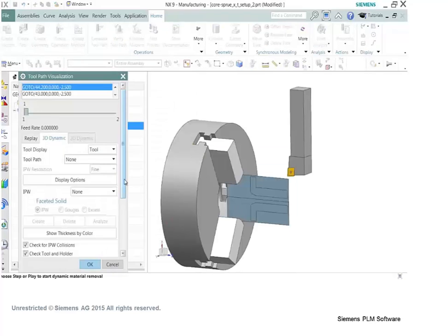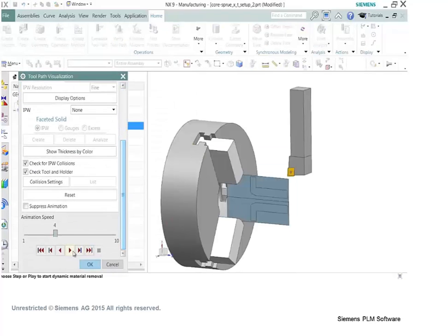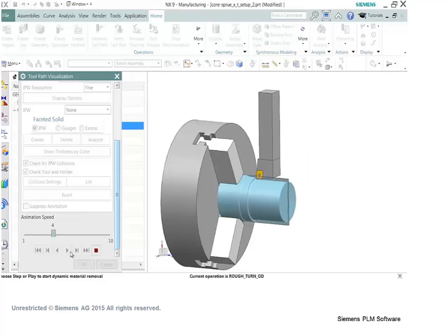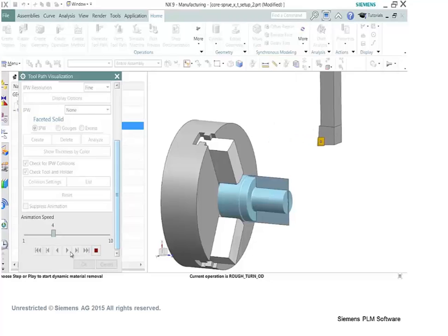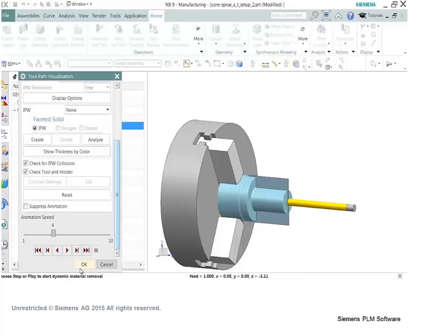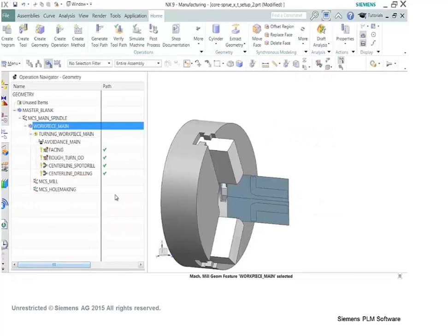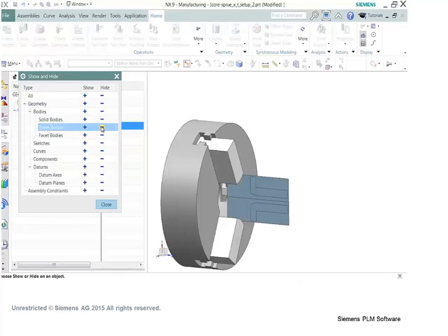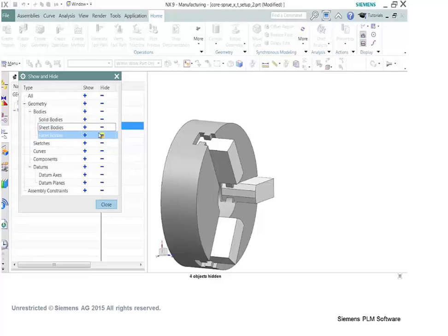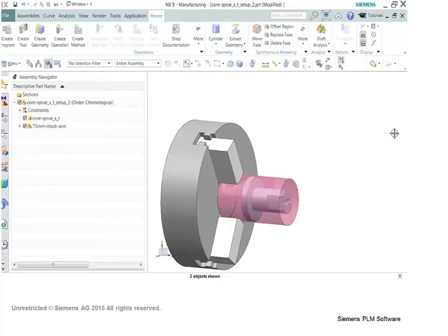Of course, we can go through and now simulate it, so we're verifying the material removal. This also is going to let us take the same material, the way the part's already made, right into milling. So this may be a big difference for you guys using Delcam, going from PowerMill. You'd have to take this part into PowerMill, and then you're not sure maybe where the stock is and how it was finished, etc.